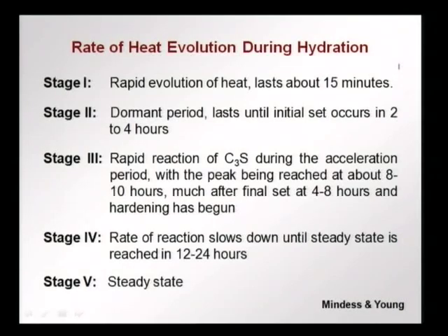So in stage 1, which lasts very little time, usually during the mixing process, we have this first peak coming from the ettringite formation, then we have a dormant period which lasts until the initial setting occurs in about 2 to 4 hours, and this is the period where we should finish the transportation and the placing of concrete, so that when the network of hydration products is forming, there is no disturbance to the concrete itself.